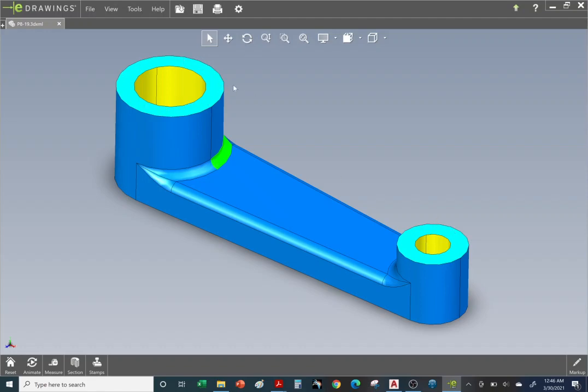So both of these will be parallel, not in the same plane, but parallel to each other, and also in this case parallel to the base, to the bottom, because most likely something needs to attach to these surfaces, or mate up to another part at these surfaces, and same thing with the bottom. Most likely it'll have to mate up with another part and most likely bolt it together. All right, so let's take a look at the answer key.